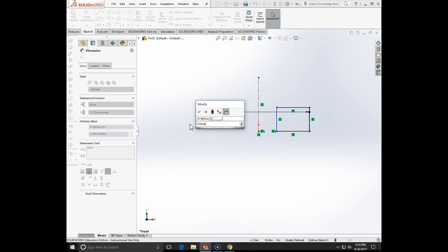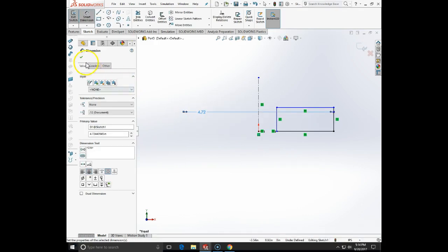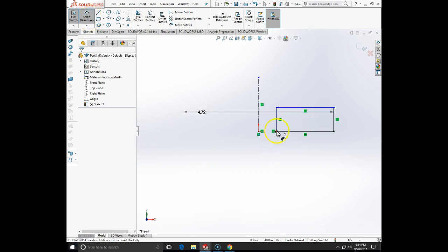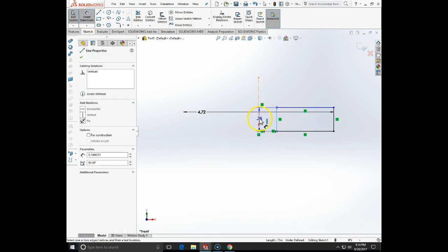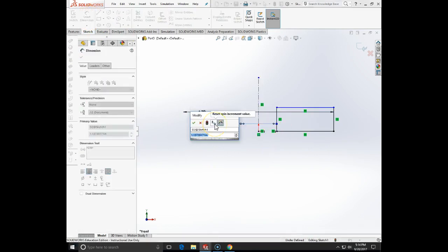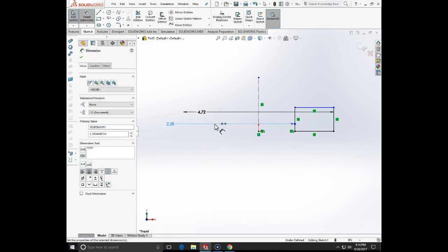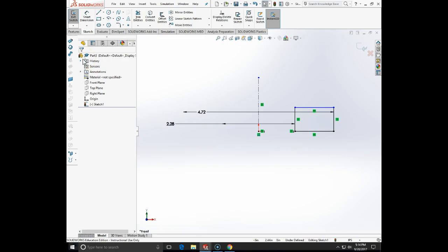And note that we haven't changed to the units of millimeters yet. Top diameter, the inner diameter is going to be 58 millimeters. And as you can see, because the inner diameter is 58, it will really be an interference fit.